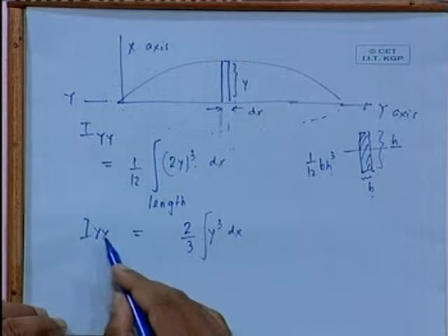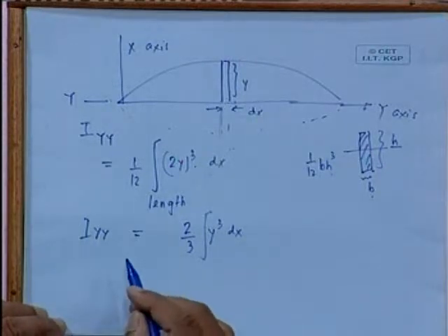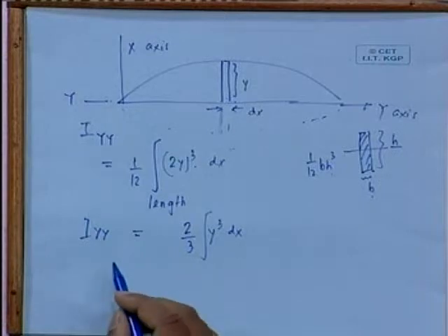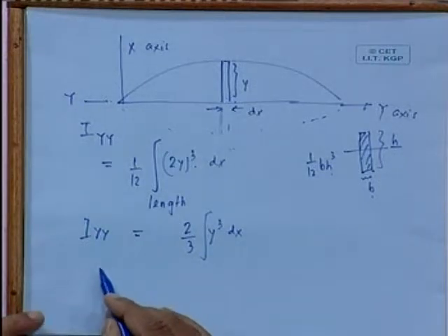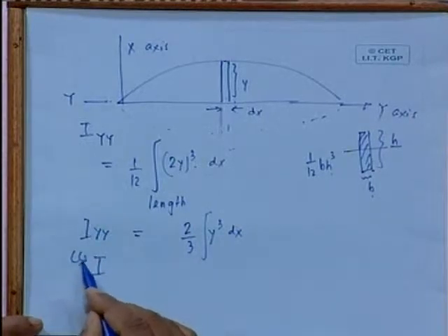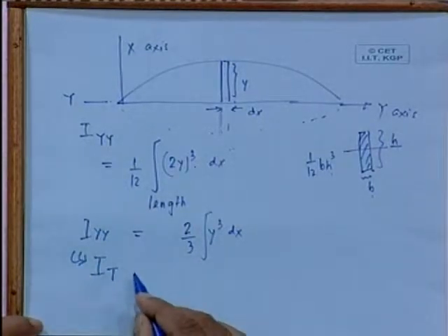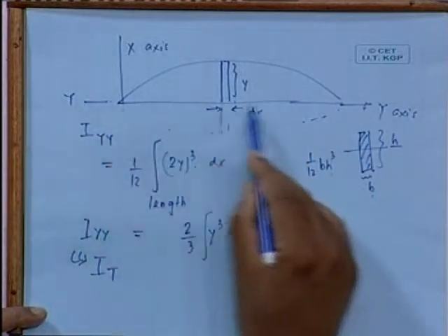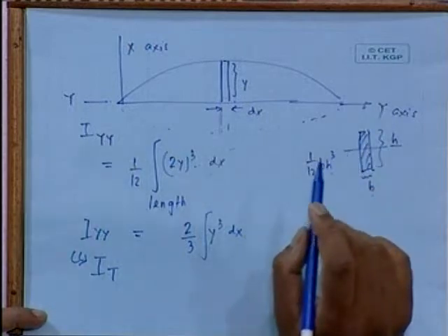A lot of people call this, it is a kind of a misnomer for the naval architecture people, people call this also IT or I transverse. Actually, this is not a transverse axis, this is a longitudinal axis. But I must emphasize this point.